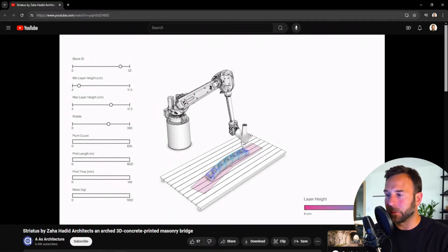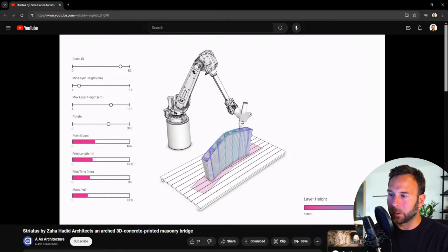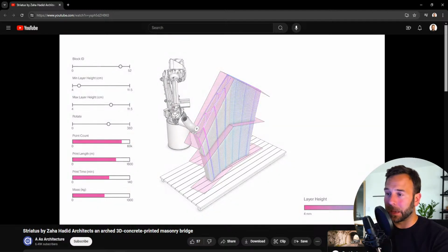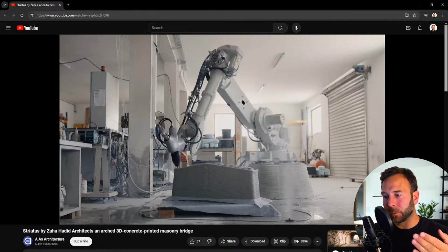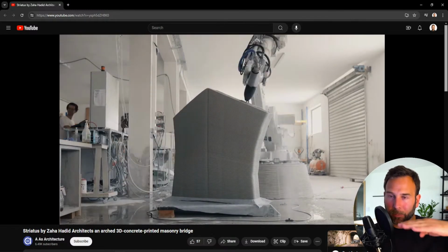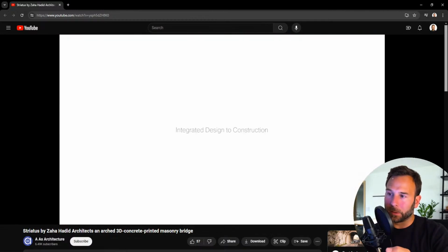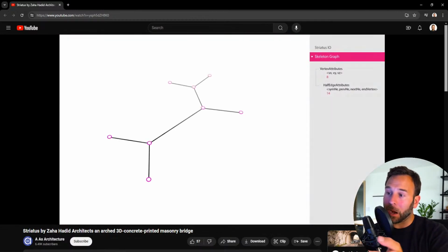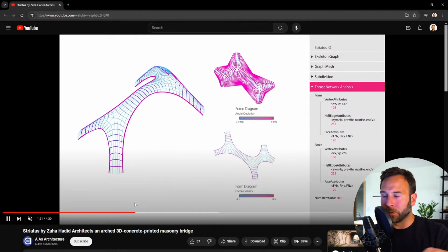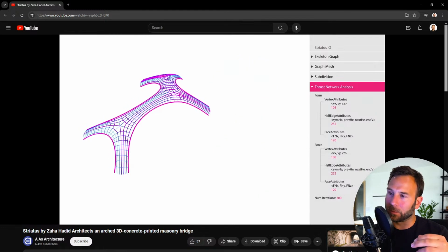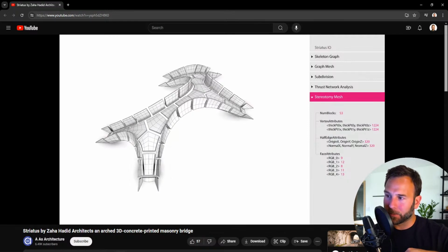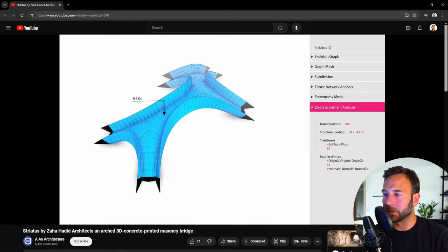So you can see for this they used a multiple axis 3D printing arm so that they can actually get that fanning. Typically in 3D printing you are limited with gantry style printers to just printing layer by layer horizontally, but with the 3D printing arm, robotic arm, you have the ability to move in multiple axes, meaning like vertical also, while you're printing a horizontal line, and kind of gives you the ability to move up while you're moving horizontal, is what I'm trying to say.